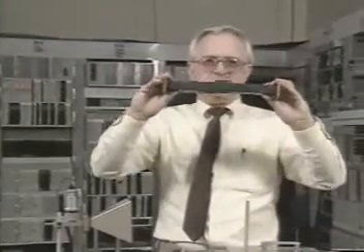Waveguide doesn't have to be hard, rigid. It can also have flex. This is a piece of flexible waveguide, corrugated inside, has a little more loss, as you might imagine, but it can allow us to make adjustments in the alignment between a transmitter and its antenna at the top of the tower. As I said, as the curvature of the earth interferes with it, we have to keep raising the antenna up, higher and higher on the tower.